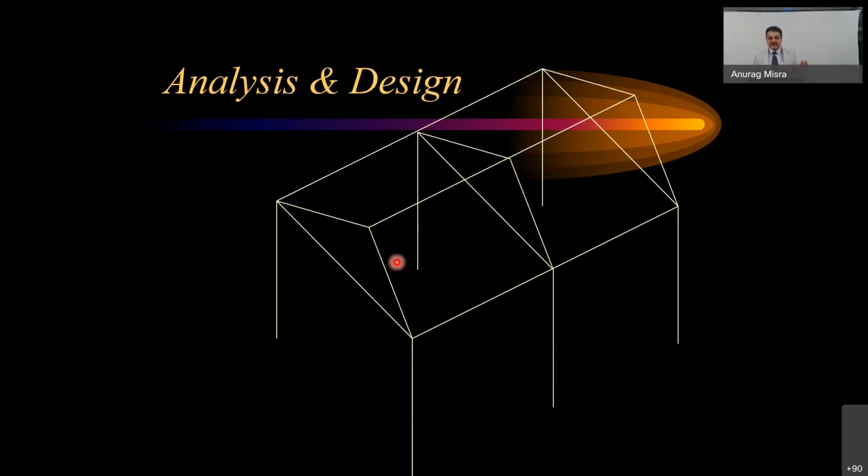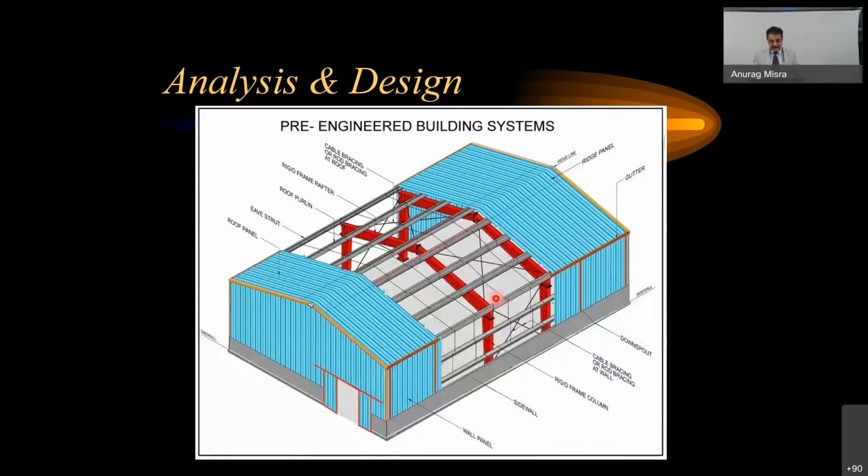Buckling is not the right word. Warping of the members, etc. And they start creating functional issues. So what I mean is that if you are going to design this, so if the joint is going to be created at, let's say, 40-meter length, then the temperature variations have to be considered, and additional stresses which are going to be created along with the load and without the loads have to be considered for proper functionality of the buildings in service. So this is one of the typical examples with different kinds of components.